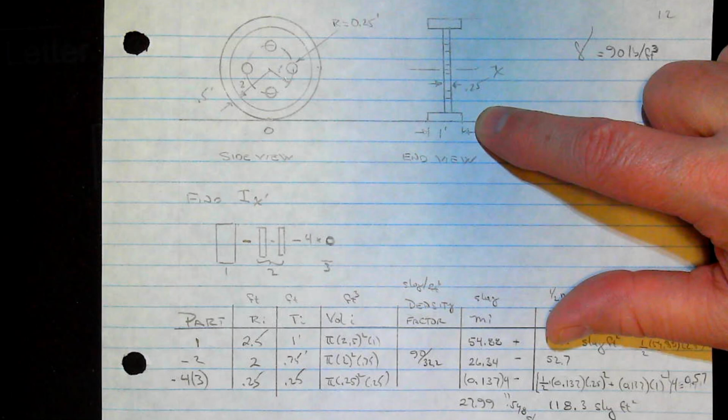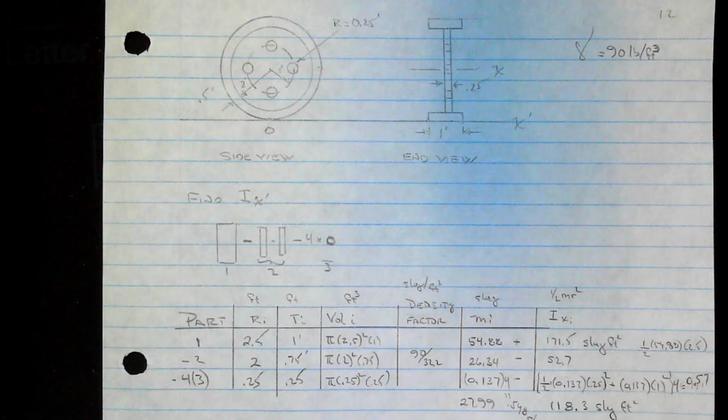And then we have the countersunk one. So it's pi over 3. Its base is also 200 millimeters. Square that, times the height, 600, divided by 1,000 cubed, 0.025 meters cubed. Now that we have that, multiply every one of these by 200, and we will have the mass. I'll show that on the next page.